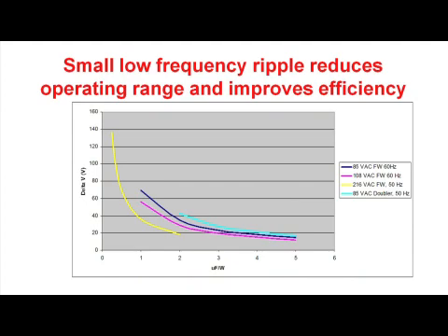So I've done a couple simple charts here to show the impact of the value of the capacitance versus the minimum range that you have to operate over, or basically the change in voltage on that cap at several different line conditions. So what I've done is I have normalized the value of the capacitance by the output power of the power supply. For instance, if you had a 5 microfarad input cap and you're only putting 1 watt out of the power supply, you would end up over here on the curve on 5.